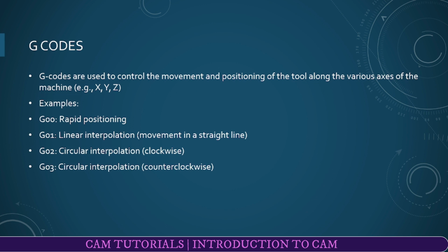Say I want my tool to move from X0, Y0 to X10, Y10, and the radius of my curve is 10 millimeters, and I need to follow clockwise interpolation.